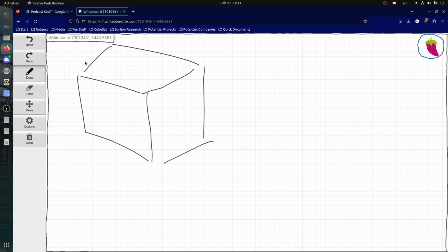So the next thing is the attitude determination stuff. The first thing is the star tracker. This is the main way of figuring out where you are. To put it simply, you have a camera, and within that camera is a database of every star in the sky that is bright enough to be detected by the camera, or usually less, but you get the idea.